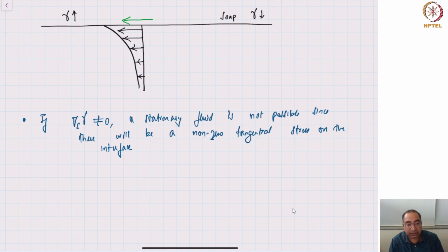So we will end this lecture. What we have done in the last few lectures is derive the jump conditions at an interface, both with and without surface tension. The equations in the bulk are the mass and momentum balance, that is the Navier-Stokes equations for incompressible Newtonian fluids. So now we have the equations in the bulk, and we have the boundary conditions or jump conditions on the interface. Now we have all the necessary machinery to address some interesting problems in interfacial fluid mechanics.